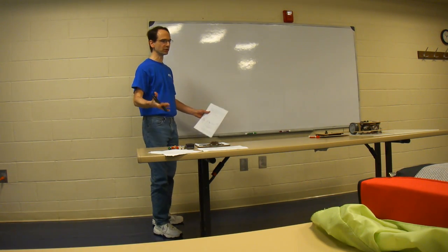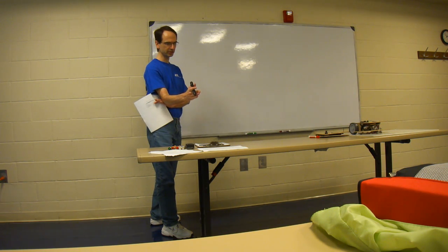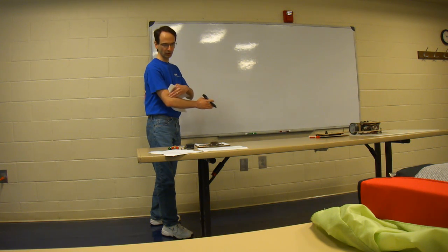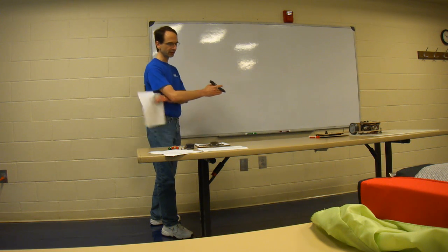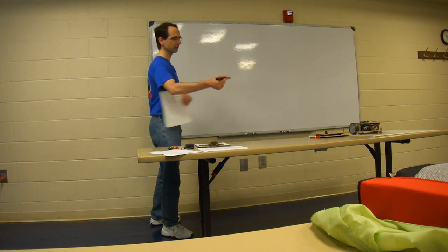And you would be doing the same thing with, say, an arm. You've got an arm and you want the arm to be here, and you're sensing its position, say with the angle. So you've got a sensor that's checking the angle, and then you've got a motor. As we're moving towards the goal, we're sensing the angle, changing the angle with the motor, sensing the angle, and changing it.